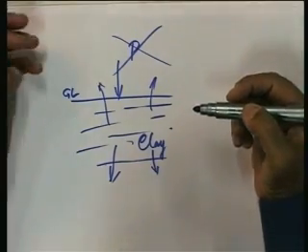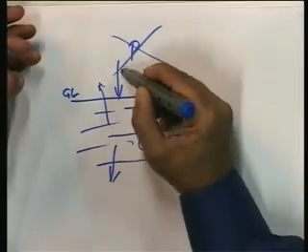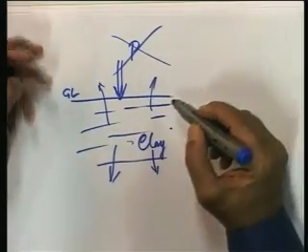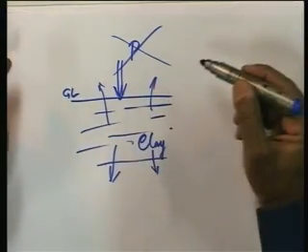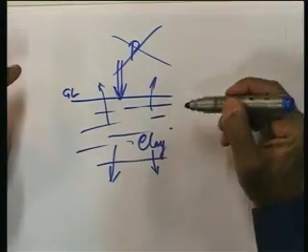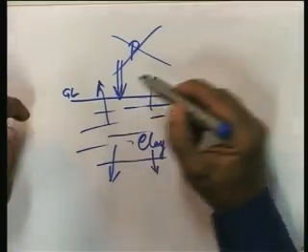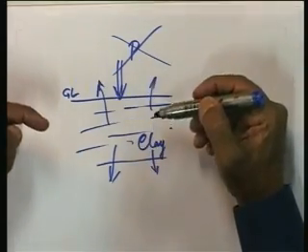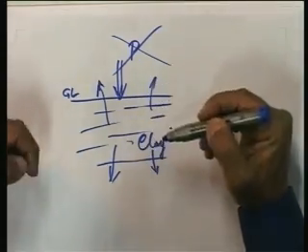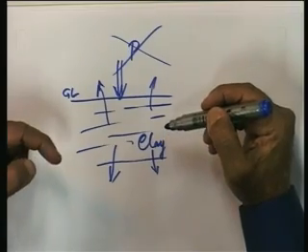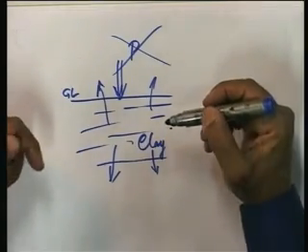On the other hand, the moment we apply a load, since expulsion does not take place immediately, it implies the load is transferred to the water first, because the water is incompressible, and until it deforms or goes out, it cannot transfer the load to the solid grains.